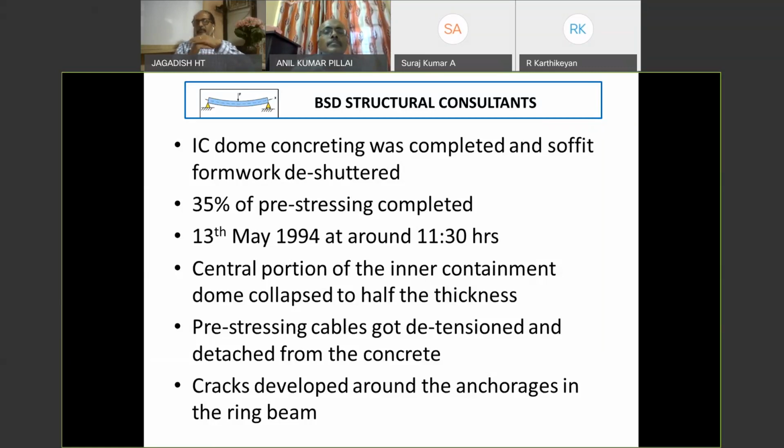When it comes to pressure, because of the higher pressure, to avoid crack formation, we are stressing the dome on the wall and inducing compression in the dome on the wall, so that when the pressure comes up, the compression gets released and we don't come across any tension points.